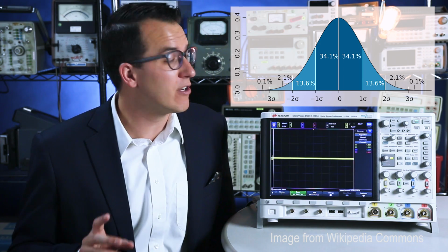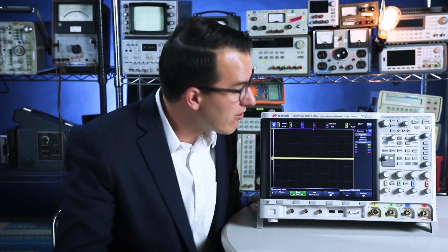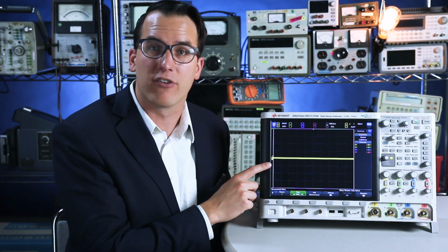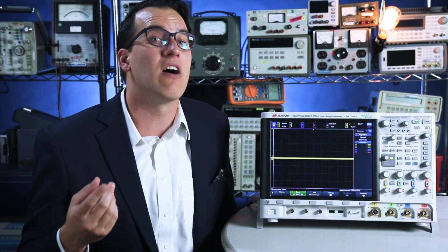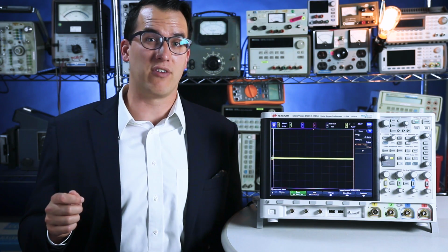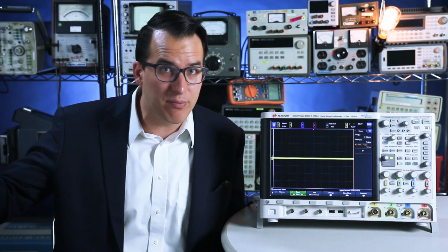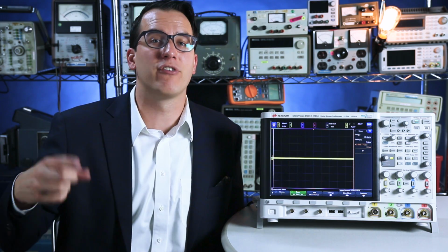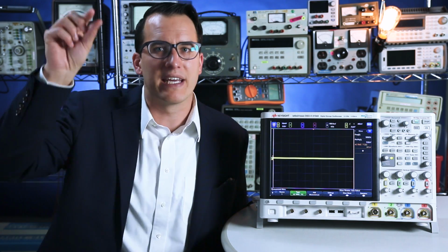distribution. So to measure it, you first want to zoom in to the smallest voltage per division setting on your oscilloscope, and then you want to turn on an AC RMS measurement. Why wouldn't I just use peak-to-peak voltage instead of AC RMS voltage? Well, peak-to-peak voltage is not an accurate way to measure noise because it's a Gaussian distributed waveform. So the more captures you have, the higher and higher your noise is going to get because you're going to get lucky and hit farther and farther out on that tail.